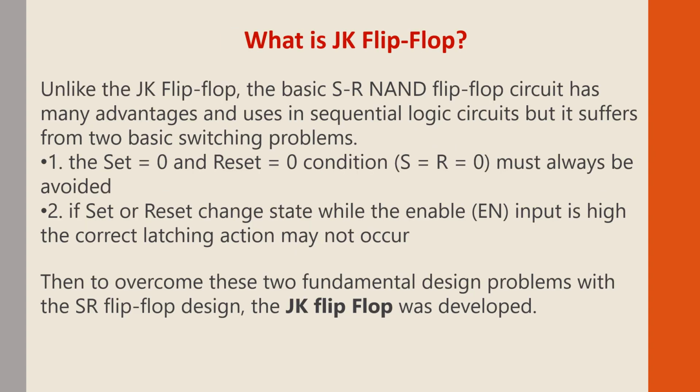Now we talk about what is JK flip-flop. Unlike the JK flip-flop, the basic RS NAND flip-flop circuit has many advantages and uses in sequential logic circuits, but it suffers from two basic switching problems. The set S equal to 0, reset R equal to 0 condition must always be avoided. If set or reset changes state while the enable input is high, the correct latching action may not occur.